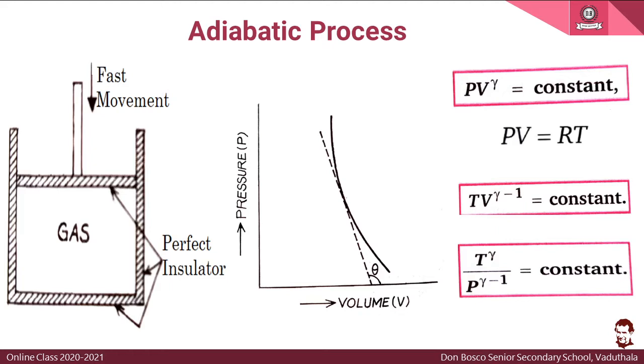See how the system is taken. It is perfectly insulated. Because of that, no heat transference is taking place with the surroundings. Therefore, when the gas is expanded, it will be cooled, temperature reduced. When the gas is compressed, temperature will be increased. Thus, the process in which the temperature change is occurring is called adiabatic process.